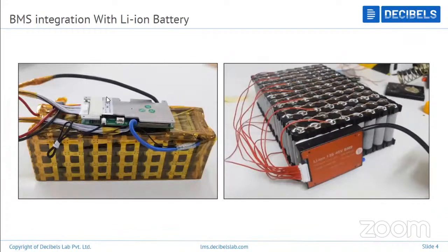So you have series connection and discharge. Again, discharge current is based on your battery pack, right? So for example, this is a 30Ah battery pack. 30Ah means at nominal it will be able to give you 30 amps of current. Now, let us assume the cells are 1C rated cells, right? So 30 amps is the nominal capacity, or the max it can give from the battery pack. So you would choose the BMS based on that. You would choose a BMS such as 13S, 30 amps discharge current, right?